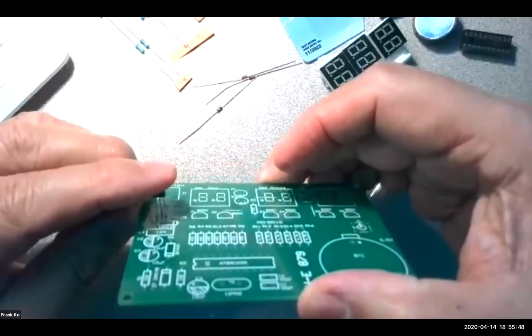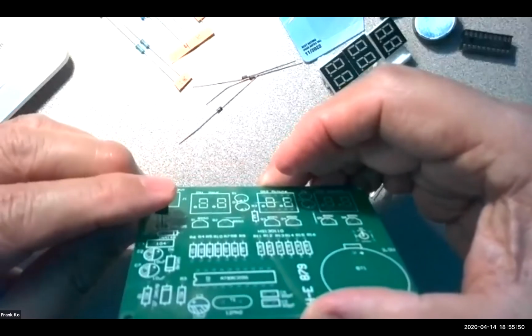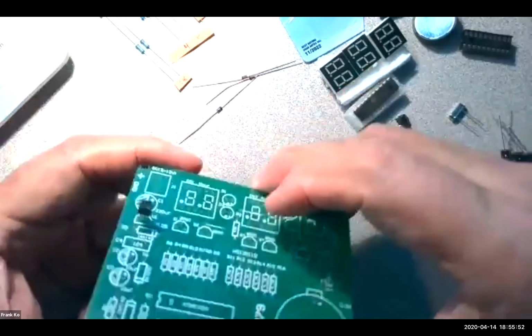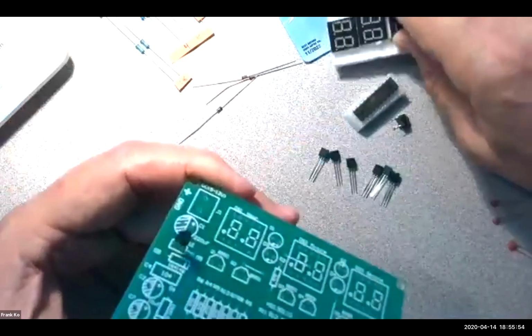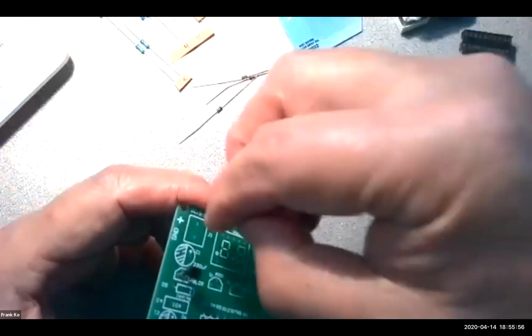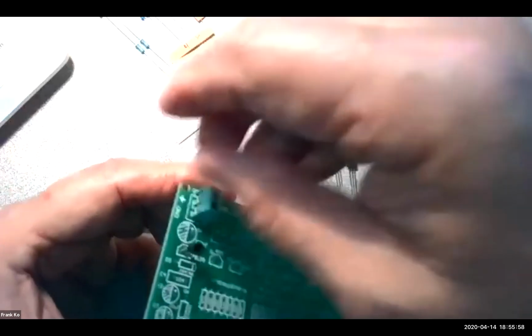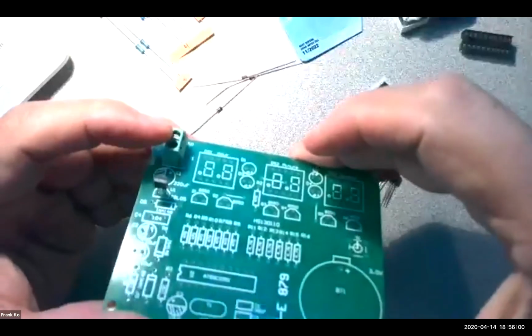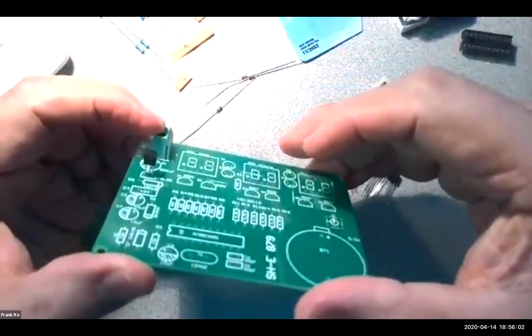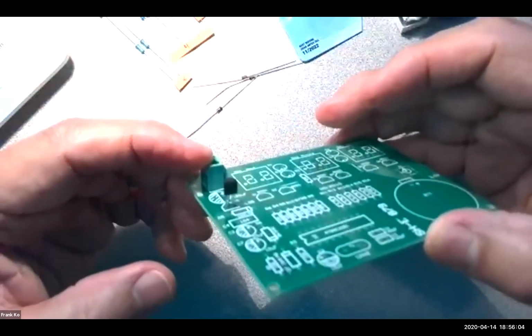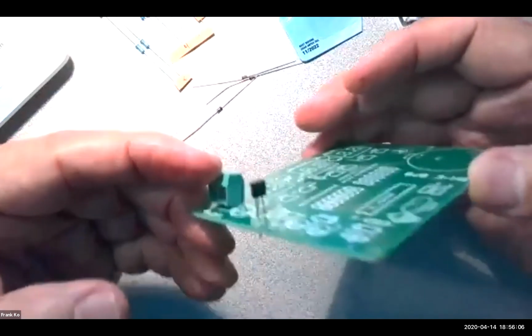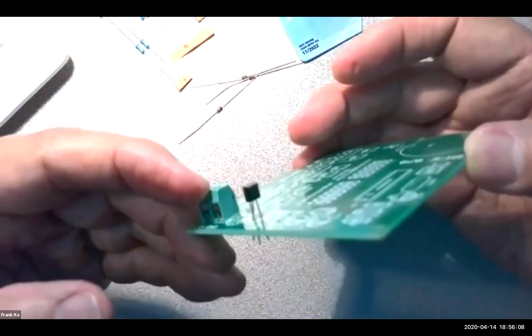And you push it down. It doesn't have to go very far down on the board. I don't recommend it to go too far down on the board because you have other things that stick up off the board. So this particular power connector is going to stick that high up off the board. If you make your transistors the same elevation off the board as your power connector, you're doing fine.